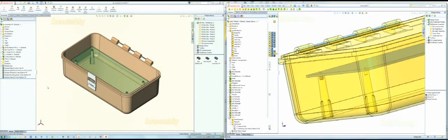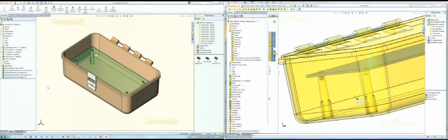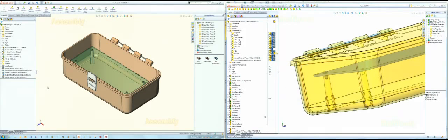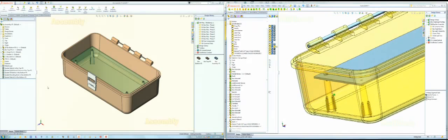And then I'm also going to add a washer and a screw. These are all parts that are just on the drive. They're separate parts, but we're bringing those into this part. And then I did the same thing. I used that same sketch pattern on the printed circuit board to do a pattern of this, because when we did the mounting boss, it was the pattern of a feature, and now this is a pattern of a body. So they're two separate patterns.